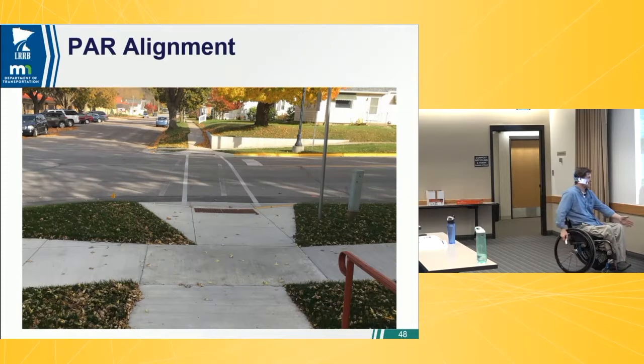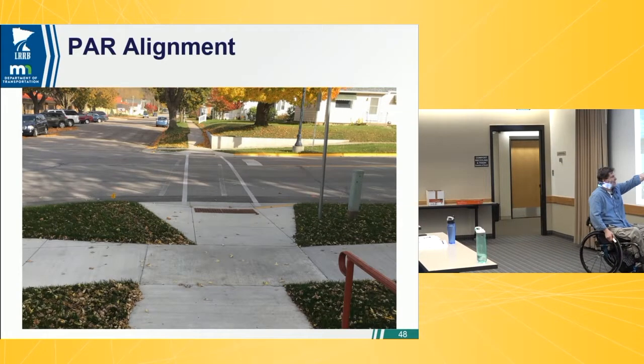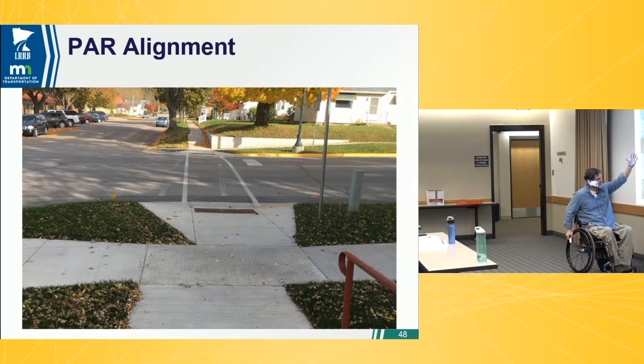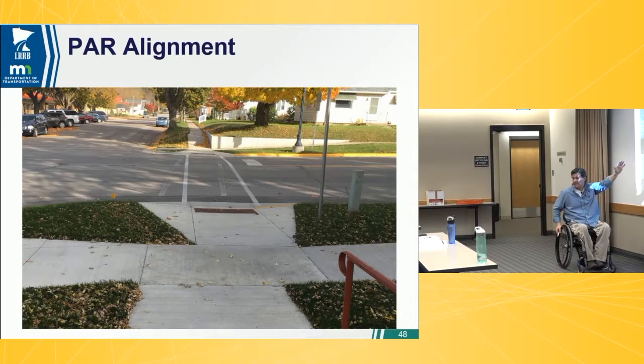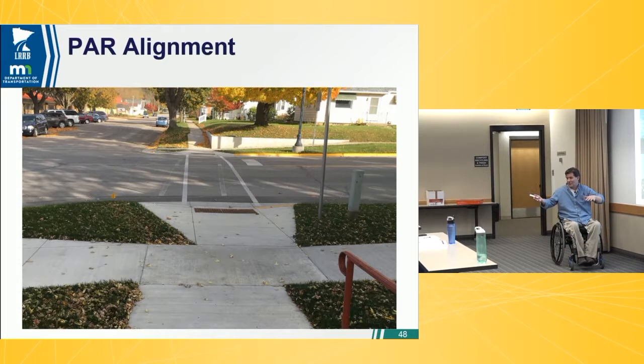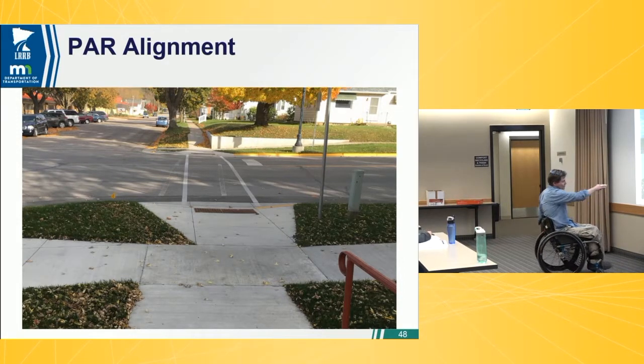If you're progressing down this sidewalk and you just go straight, if you're in a chair, you're probably taking a digger. For the visually impaired, it's kind of an ankle breaker, not a good deal. Also for the able-bodied, if you're not paying attention, checking your iPhone, whatever, it can lead to problems, and it's not too intuitive for maintenance either. One thing I like to mention here is that we're doing this 2-foot shift over a 5-foot landing.